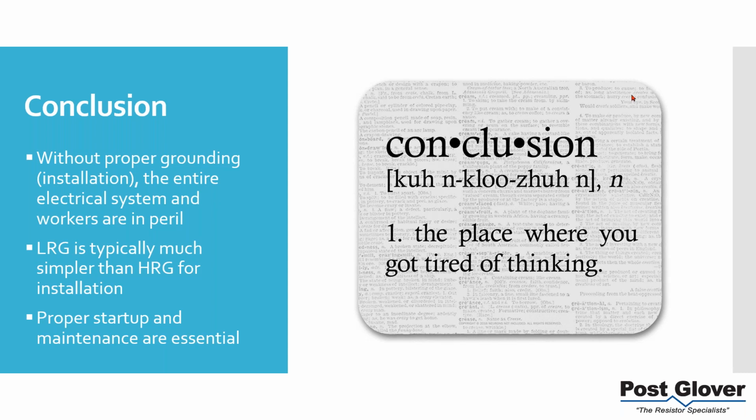I was just going to throw out, alternately, you could sum up all your cable length, all the associated capacitance per foot, all the insulation in your motors, and manually add it together if you're so inclined. Yeah, maybe I misunderstood the question. Yeah, that's how you could definitely calculate it.